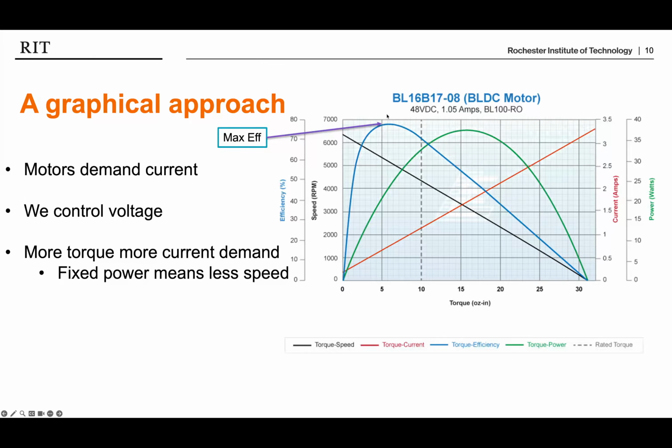So all motors will have this peak efficiency, and they do not line up with our max power. So again, we have peak efficiency, we have max power, and then the other thing we have over here is this point where we have absolutely nothing going on. We're just heating up our motor. We're getting ready to turn it into melted metal, and this is all occurring at our stall torque.